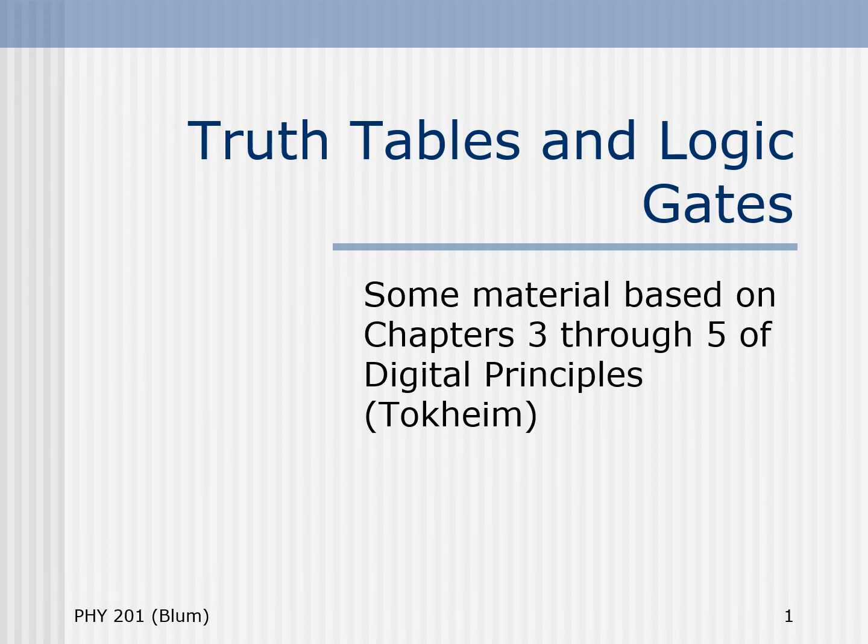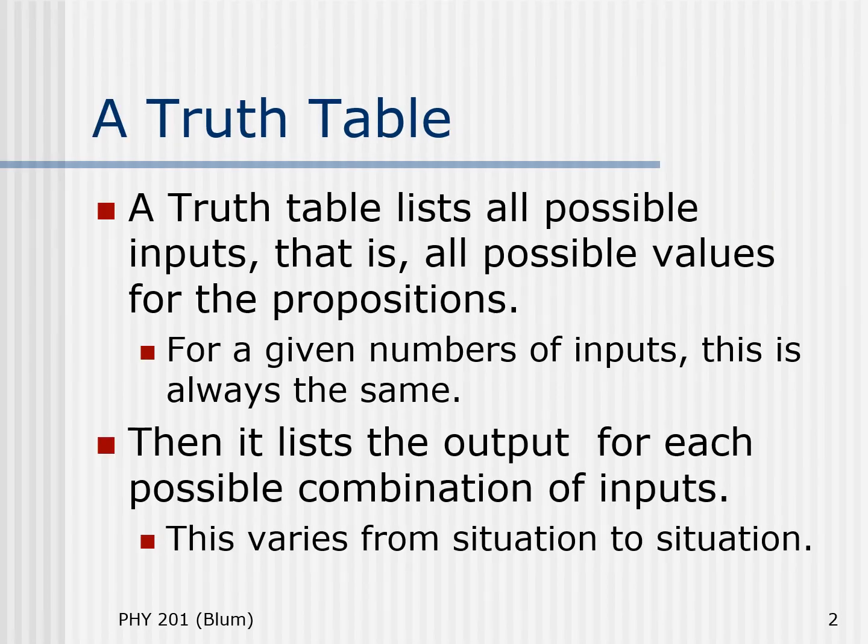In this presentation, we will discuss truth tables and how to realize them using logic gates. A truth table is going to consist of two sides, an input side and an output side. The input side is going to list all the possible combinations of zeros and ones that can occur. And the output is going to be some particular scenario of zeros and ones wanted for that situation.